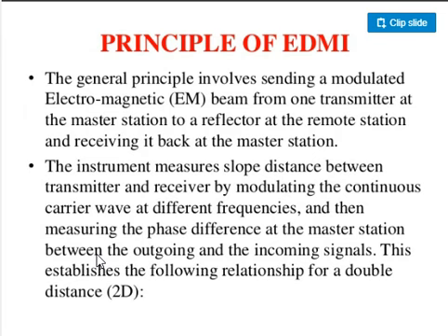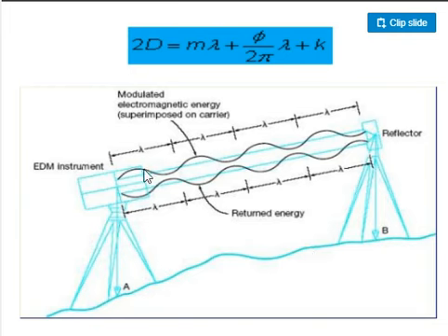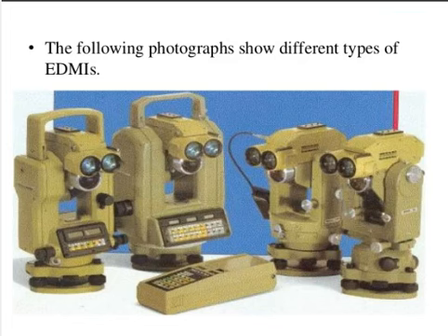So it calculates the time taken from the starting to the time taken to get back. So the time is two times; if you divide it by two, you will get the average time. So it is taking two calculations at a single time, and it can give you more accurate values, as we have the transmitter and receiver in the instrument itself. The instrument propagates, the reflector sends it back, then it calculates the value. It calculates double the distance, and that gives you accurate values.